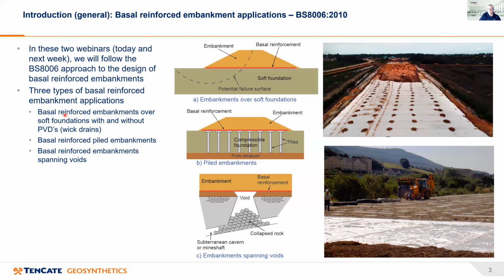Now, just a general introduction to basal reinforced embankment applications. What I'm going to refer to quite a bit throughout the talk is a code of practice called BS 8006. If you're not familiar with that, it's a British standard code of practice on reinforced soils, and one of its chapters deals with basal reinforced embankments.